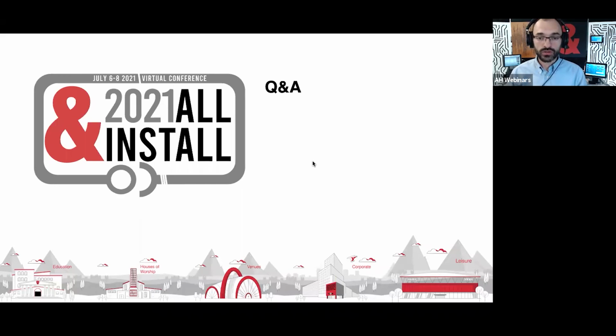However, if you can afford to have individual microphones, each with an echo cancelling instance inserted in the input channel, that is certainly the best possible scenario in terms of improving the quality of the echo cancelling and therefore the quality of the call. And the reason for that is that, as we discussed today, each single microphone will have a slightly different impulse response from the room for different paths of the reflections going into the microphone. If you move one microphone relative to the others, you will change all of that again. And so if each individual microphone has got their own adaptive filter chasing up the impulse response, it will work in a much better way than trying to calculate the overall impulse response from all of the microphones in one go. But it's entirely possible to do it the other way as well.